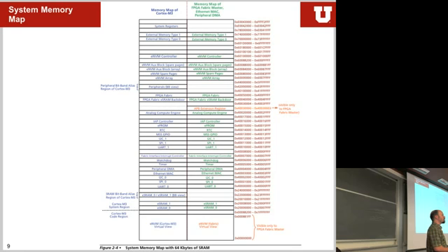Yes? What benefit would that give you over just using a mask, like an AND mask or an XOR mask? Sometimes you really don't want to touch other bits. Even if you AND it, or if you, for example, read something out of it, sometimes you really only want to go and read one bit and not touch any of the others. That's when you would go into this particular area. Okay, so yeah, I guess with a mask, you read it out. Exactly. Mask and stuff, and then write it back. Yes. This will be one instruction done. Correct. I rarely use it.